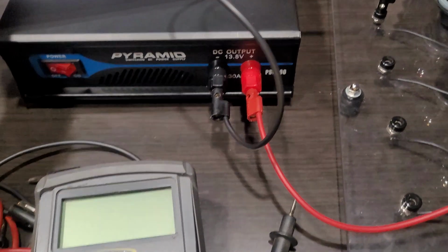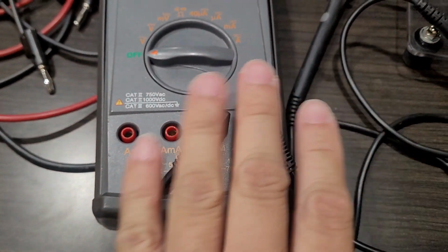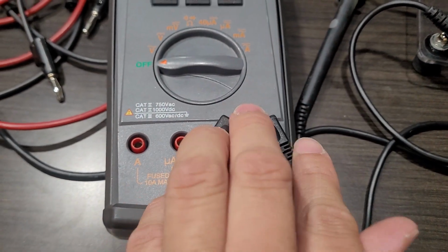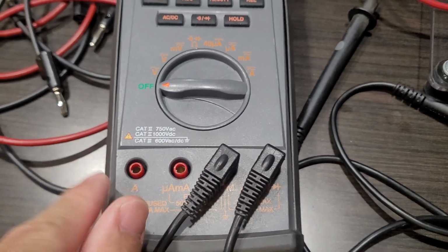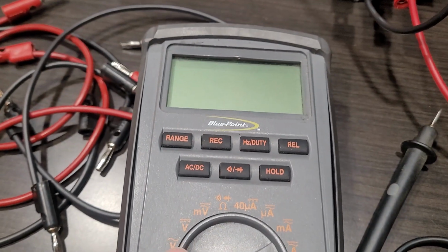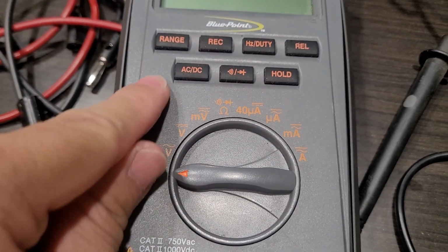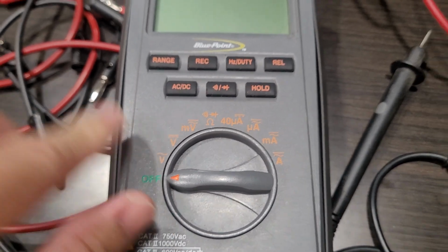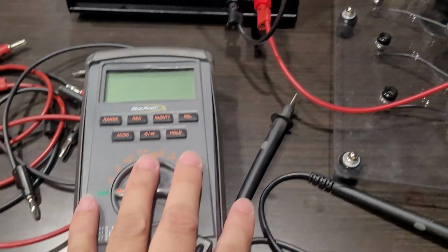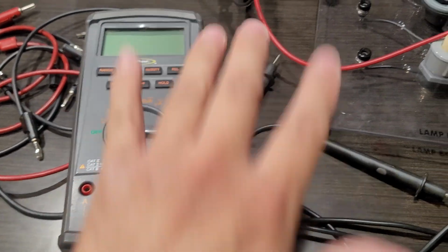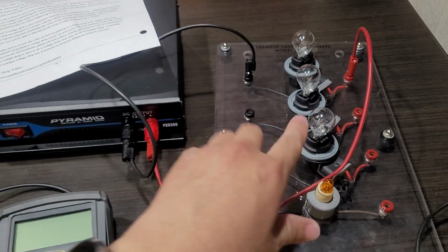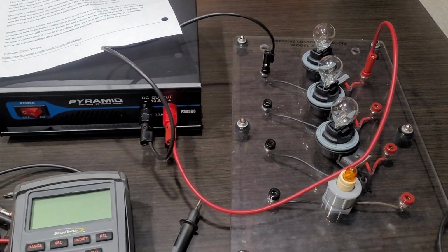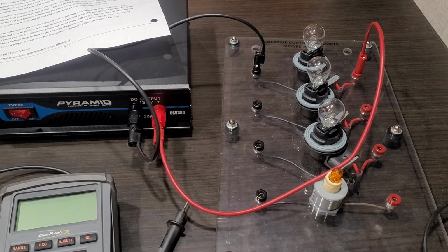Again, a couple of things that I see students do mistakenly all the time. They will not plug these in all the way in. They won't get a correct reading, or they'll plug it into the wrong outlet. The second thing they'll do is they'll put it to the wrong setting on the dial. So make sure you put it to the correct dial. And then lastly, make sure you put the test leads of your digital multimeter here, the red and the black, into the correct spot. If you put it into the wrong spot, again, not an invalid voltage.